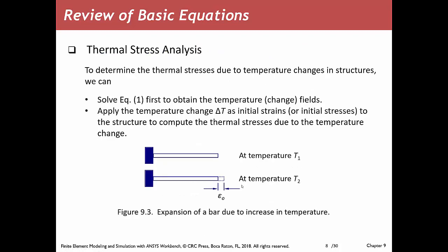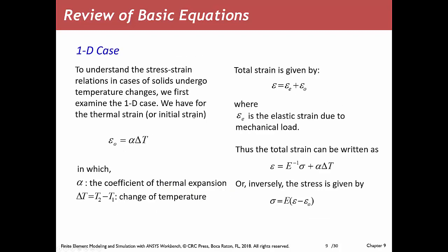And then the third thing is the thermal stress analysis. We all know the equation for stress, which is sigma equal to E, the modulus of the system, multiplied by the strain. This is the general one, but due to the temperature variation from the heat source, we have stress that develops due to the temperature, so variation in temperature multiplied by a coefficient of thermal expansion. In this case, our epsilon is going to have two components. One of them is the elastic strain, or strain due to mechanical loading, and the other one is due to thermal loading.